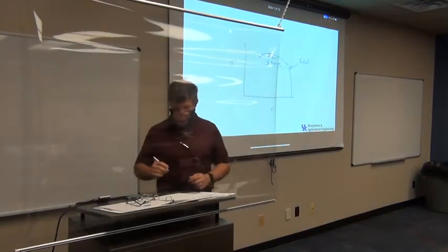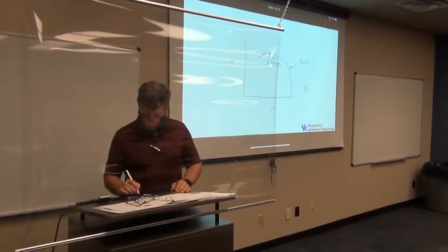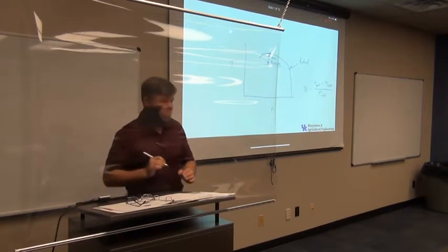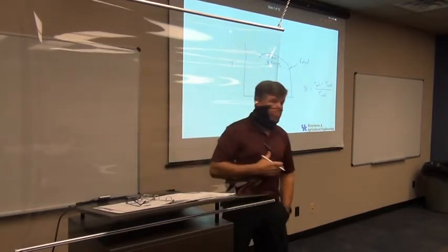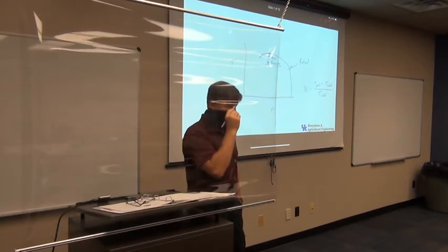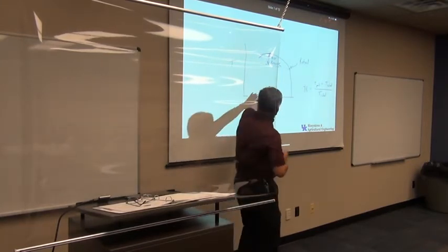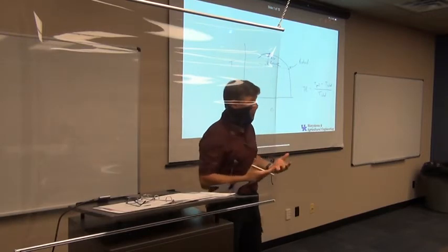Okay? And it's a percentage. So you can calculate the torque rise, TR, torque rise or torque reserve, as a percentage. It's basically the peak torque minus the rated torque at rated speed, or rated performance, divided by the rated torque. So it's just a percentage above that rated torque, whatever that rated point is. This is a fairly significant performance indicator, and people look at it carefully for a lot of engines, because the torque rise, the torque reserve, and how far to the left it is will tell you how you can utilize that engine.